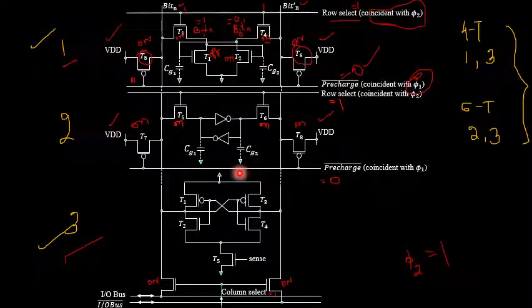In terms of the read operation, it has to be read from the capacitor via the inverter, then through the transistor, then back to the bus. So bus in the sense the bit lines, bit n as well as bit n complement. Again, there may be the presence of this sense amplifier. What happens when the sense amplifier is equal to 0? There is no turning on of transistor T5. Only T1, T2, T3, T4 will be present, which will behave like a flip-flop.